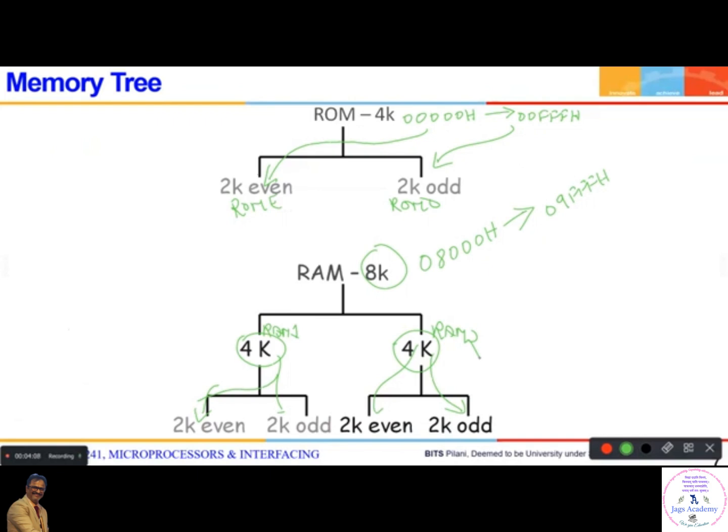Can you tell me what is the address range of this 4K? What is the address range of this 4K? Starting from 08000H to 08FFFH.